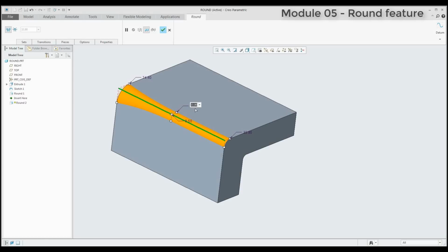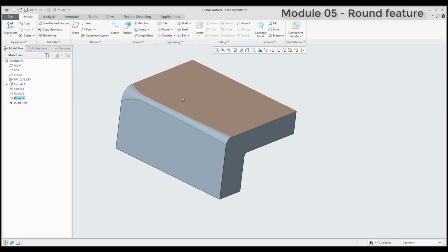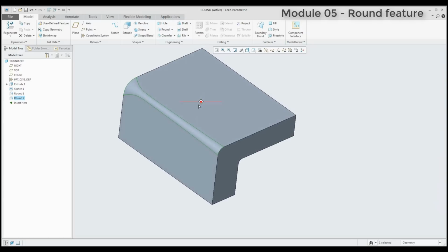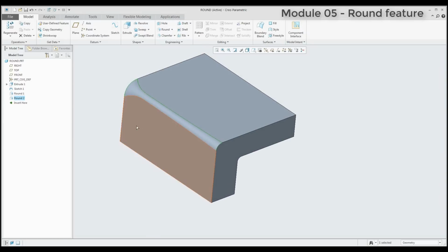Or if you specify a different kind of radius manually, or you can select and drag, no problem. And you can change, for example, 20% of the end or another side. It means 80%. Yeah, 0.8. And if you finish, the system will create for you a variable round. This variable round was created on one selected edge.